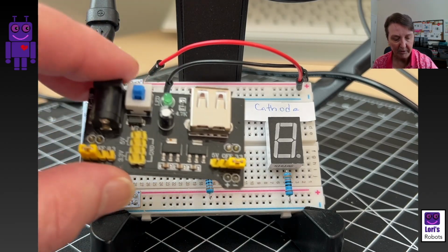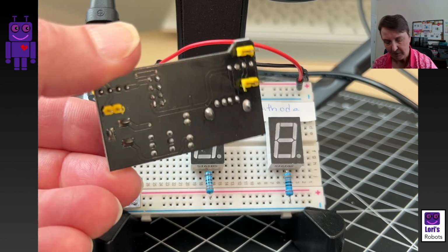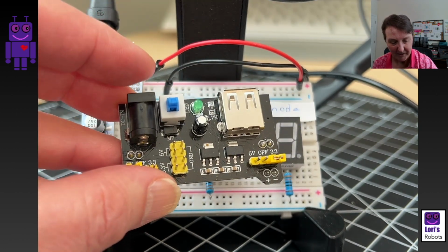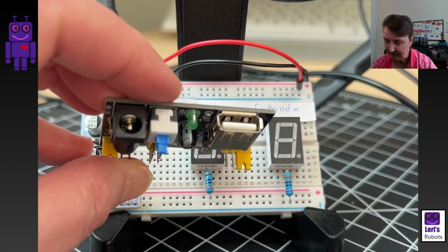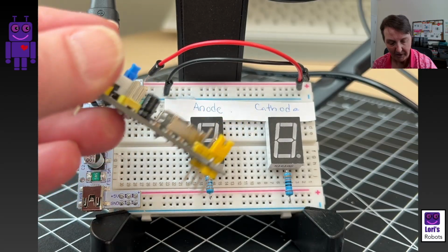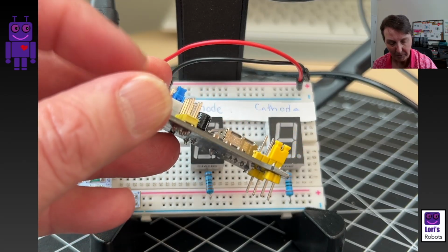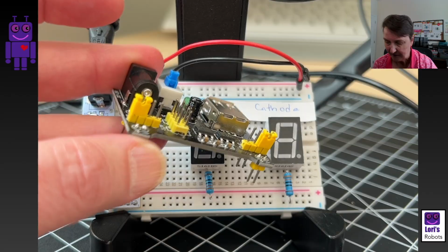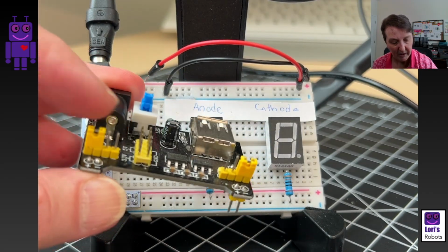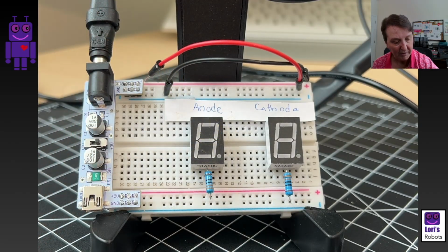I have a couple others in my lab, just checking to make sure I'm showing that. So this is one I got in a kit, and you can see the different ways I could power it. And these little jumper things are how you decide whether you're going to put 3 or 5 volts on the rail. So with this kind, you can choose to have 3 on one side and 5 on another, for example.